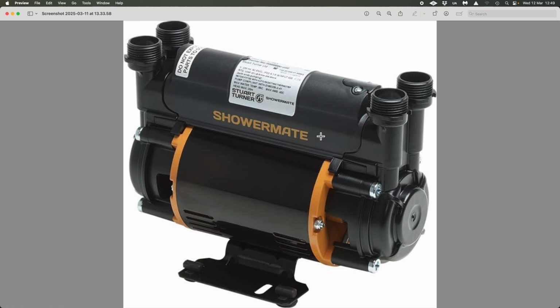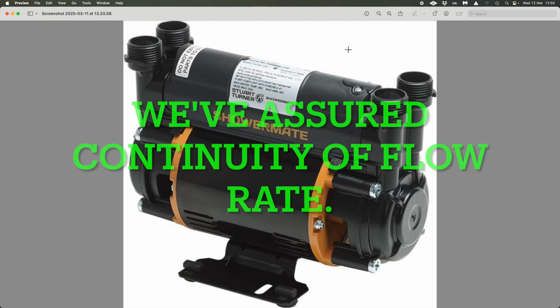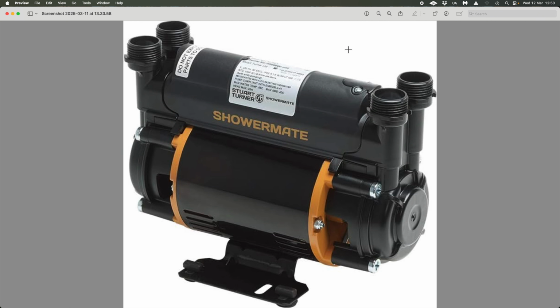So we've established that we have 15 degrees within that water tank all of the time. We've done our due diligence on the temperature of the incoming supply on a regular basis. The majority of the time, that's what it would be, as opposed to a poorly installed water main that was not buried deep enough, where the water temperature is going to fluctuate all the time, and therefore your outlet water temperature is going to change as well if you've only got a DT35 temperature rise throughout the boiler, and that will stop cycling and all sorts of things like that.